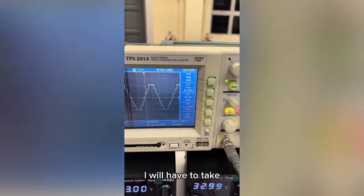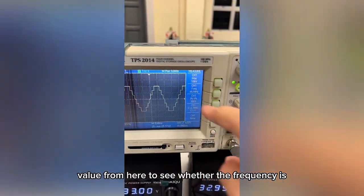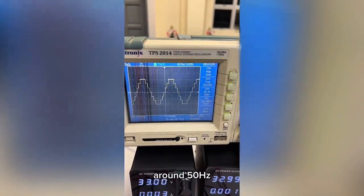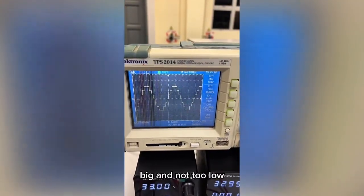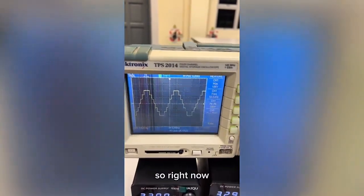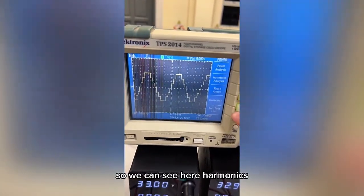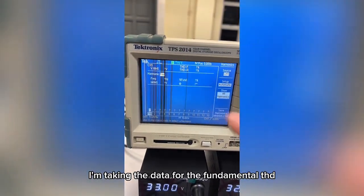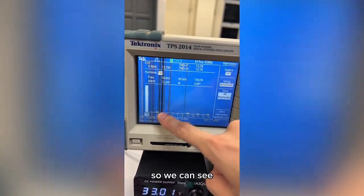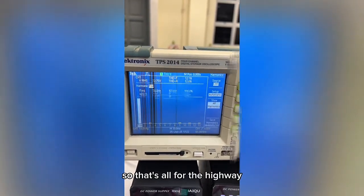Right here, I have to take the value from here to see whether the frequency is around 50 Hz. Of course there is a plus minus, but the plus minus must not be too big or too low. Right now, what I want to see here is the harmonic distortion. So we can see here the harmonics. I'm taking the data for the fundamental THD, and we can see the THD produced is 12.1%. So that's all for the hardware.